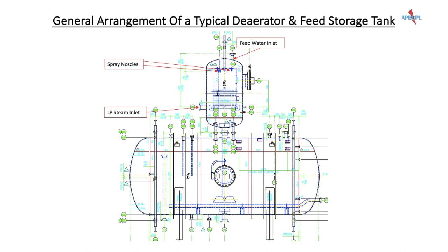The spray valves are generally made of stainless steel to withstand corrosion, and mounted on the valve body with a spring and lock nuts. The trays are assembled inside the tray box housing and held in position by hold-down bars or angles. The trays are constructed with thin sheets of stainless steel. There shall be several variants of trays in one deaerator, and are custom made for different manufacturers. Typically there shall be multiple layers of trays stacked one on top of the other.